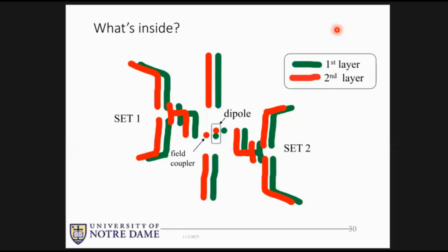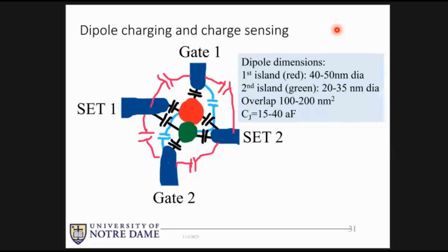So we create a dipole and we create these parasitic dots, if you wish, but it's a byproduct of fabrication. They kind of act as a field enhancer, coupling this specific device more to this dot, and this specific device more to this dot. From the standpoint of a circuit diagram, that's kind of a messy picture, but that's what really happens because you have everything coupled to everything else.